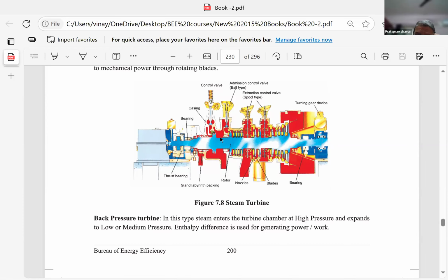Many times, the pressure reaching the last tail is, say, 50 kg, but the process requirement is of 100 kg steam. So you will not allow the steam to reach a low point of 50 kg. It is somewhere here at 100 kg, because it entered at 150, going down, down, down, 100, again down, down, 50. So at 100, I will tap it. I will put a pipe nozzle, and here only I will allow it to go to process steam.